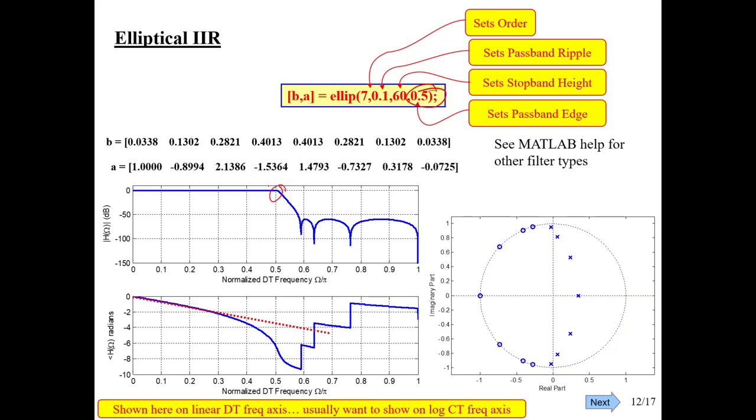And so you can see after 0.5 pi radians per second, we leave the passband. And so the 60 here sets, well, I didn't really plot this very well. I should see a minus 60, and I didn't draw very accurately there. But these heights here should not pop up above the minus 60 value on the magnitude in dB. And so that all works.